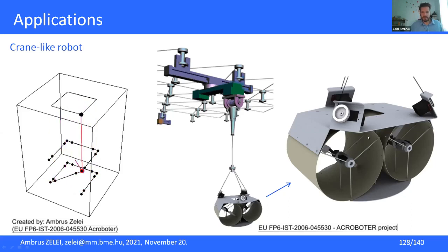So if the center point of this swinging unit has to follow a desired point in space, then we always have to turn the swinging unit in order to have the thrust force in the correct direction. So you see that at the beginning of each edge of this rectangular shape, you have to accelerate, so you have to rotate in the acceleration direction, but at the end you have to brake, you have to slow down. So you have to rotate back in order to generate some braking force. So it's quite tricky to tune the parameters and everything to work in a correct manner.